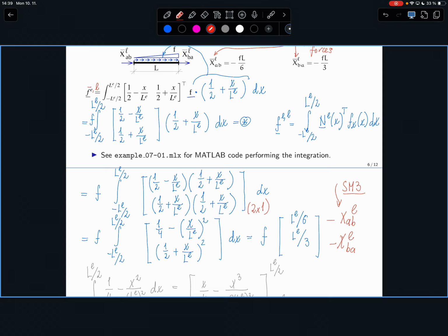And I would again like to remind you that there was an over bar, and these were also fixed end forces, if you recall, which you then took and translated to the right hand side. So this is something you do not need to do here, because these are the forces which act at nodes. The principle of virtual work does this bookkeeping of signs, which is very nice about that principle.